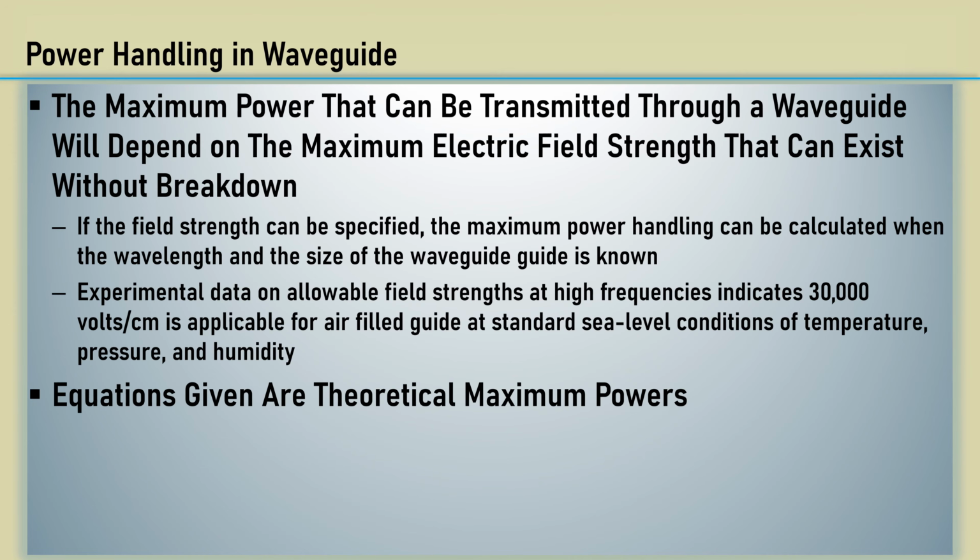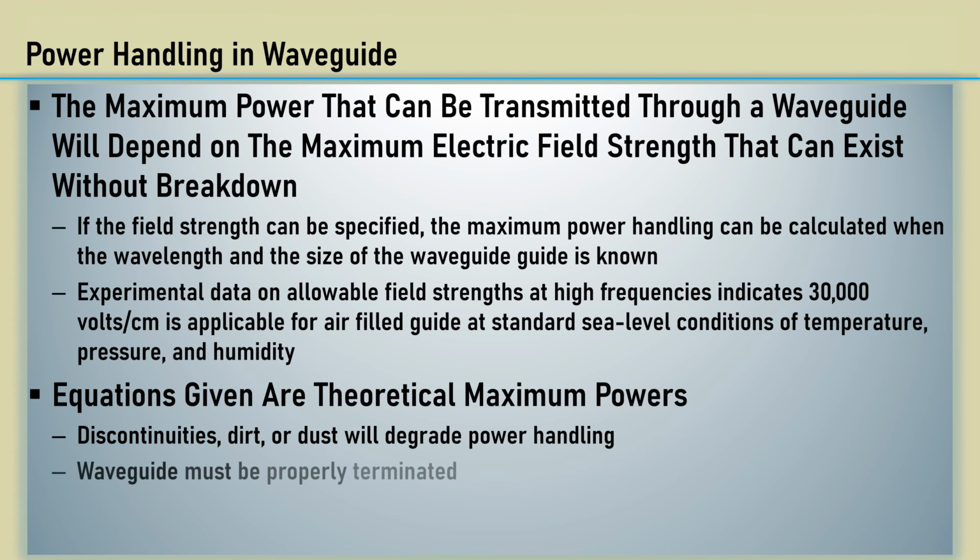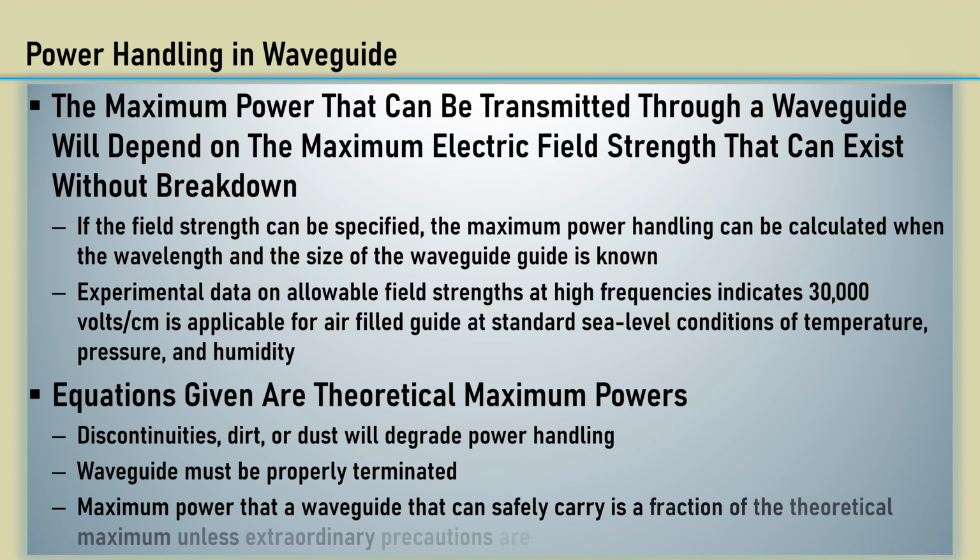Equations given are theoretical maximum powers. Discontinuities, dirt, or dust will degrade power handling. Waveguide must also be properly terminated. The maximum power that a waveguide can safely carry is a fraction of the theoretical maximum calculated value, unless extraordinary precautions are taken.